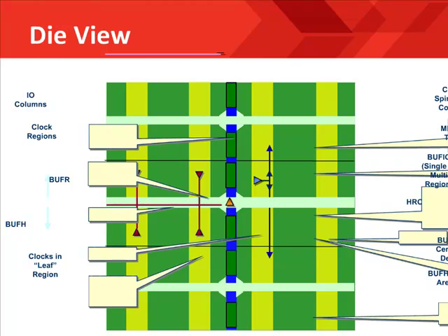The clock regions are organized into flat rectangles that are divided down the center of the FPGA by the central column. In this case, the black line separates the regions so that an equal number of CLBs is above and below the horizontal routing, commonly called H rows and shown here as BUFH's. There are between 6 and 18 clock regions in the Virtex-6 FPGAs, depending on the device density.